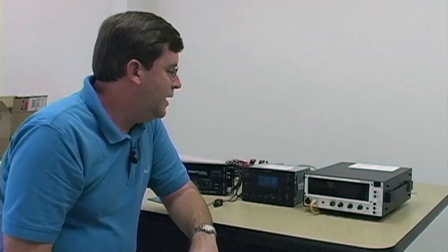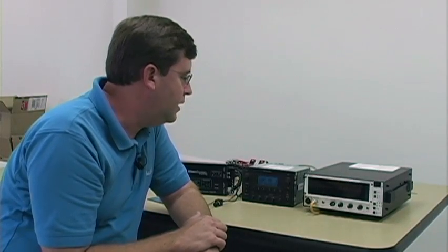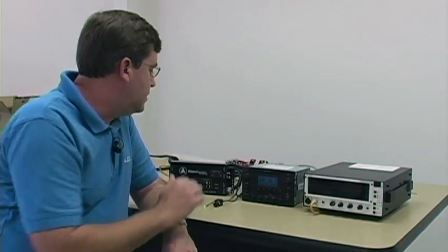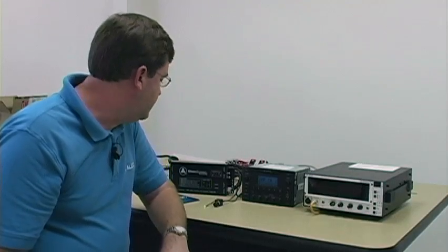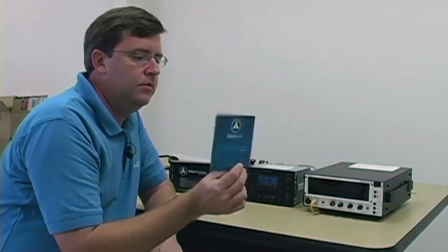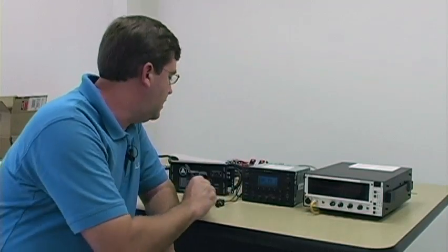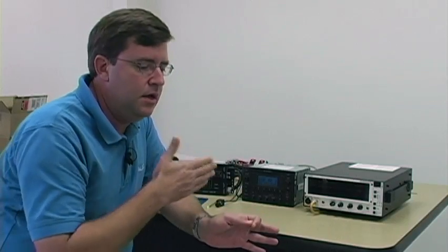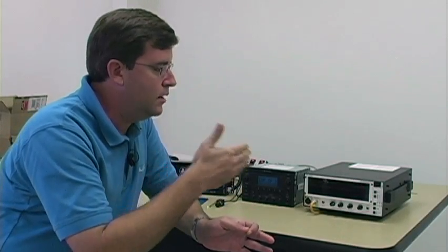What I'd like to explain now is this little test setup we have here. We have a radio from a 2002 Volkswagen, and we have our real-time analyzer, which we already discussed, and the CleanSweep DSP processor. I've taken the CleanSweep calibration disc and put it in the head unit and put track 1 on, which is a multi-tone that contains equal energy at third octave centers.